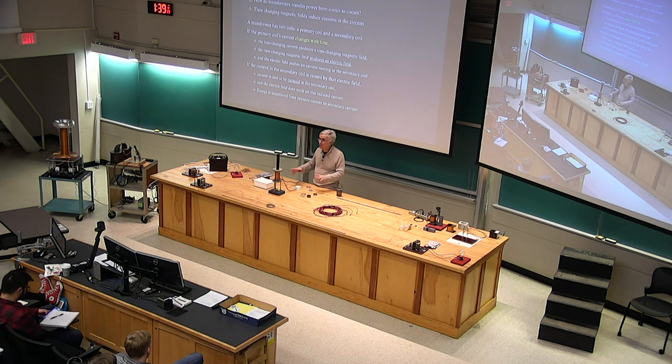And it can only do that for a very short period of time. You do not want the current to keep flowing in the same direction for very long, because if you do, it will have built up as much magnetic field as it can handle, limited by the iron actually, and then the wires will explode. So for 120th of a second, it's okay. For 120th of a second, the energy goes whoa into the magnetic field, it builds up, and then the energy comes back out and goes back to the power company.